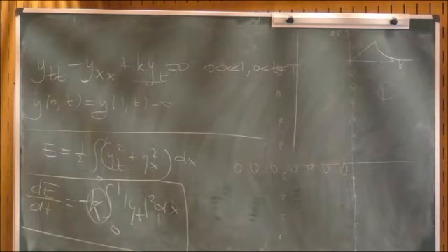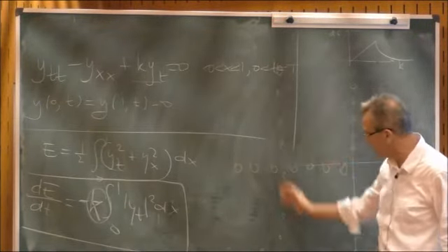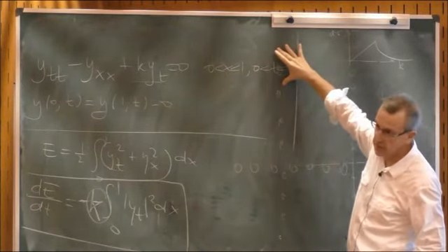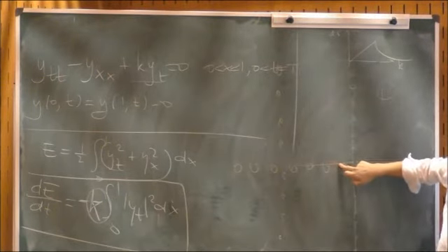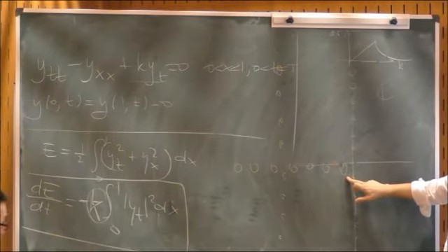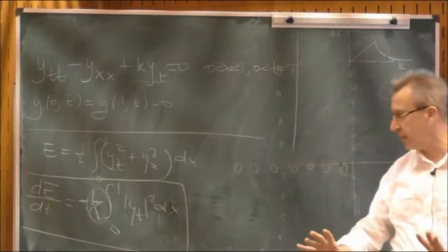You do boundary damping and you will get more or less the same. You get exponential decay. Now, the amount of exponential decay you get is delicate, right? Because, on one hand, I want to put a lot of k to push the decay to be very fast. And this is what this vertical line is telling me. For the high frequencies, the decay is very fast. Yes, but for the low frequencies, I'm paying with very low decay because of this overdamping phenomenon, right? So there is always a compromise. And it's hard to push all the spectrum uniformly, right?